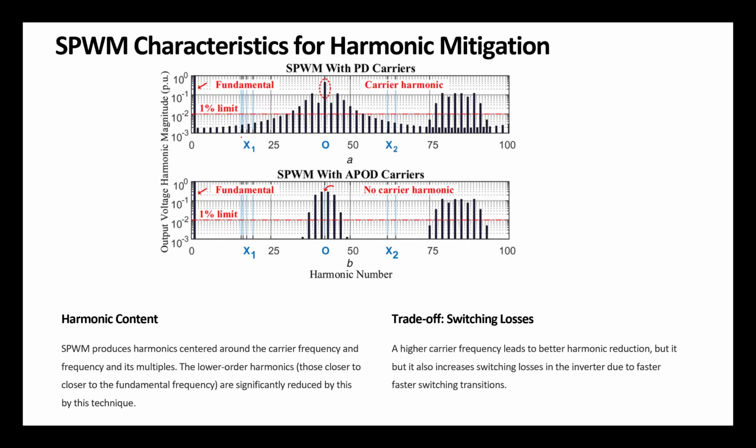So if I increase my frequency, I have to deal with that power loss and high temperature too. So there's a trade-off. I'm going to make sure that I don't go too high in order to damage my circuit. But I can manipulate that frequency in order to push the harmonics forward. Make sense?